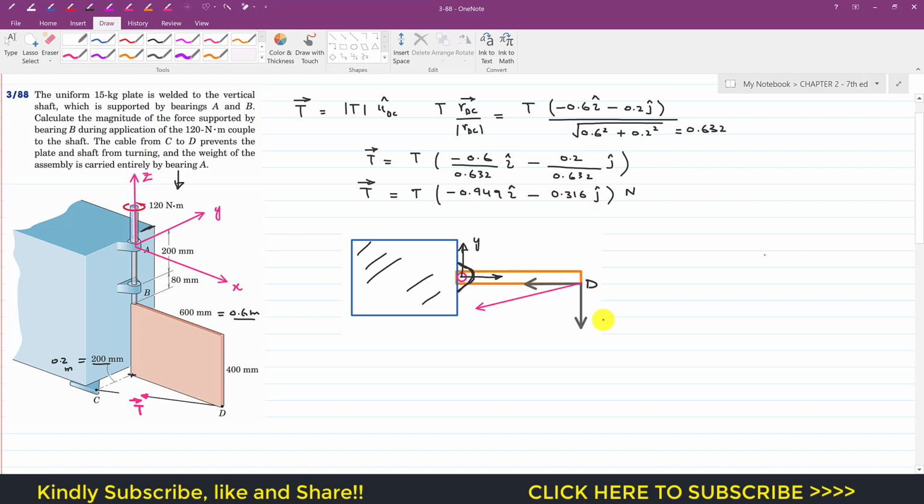So now as we can see, this is the y component of that tension T. This is T. So this is the y component, and this one is the x component. So now from this equation we can write that this T vector is equal to minus 0.949 T i minus 0.316 T j, and this is in newtons.